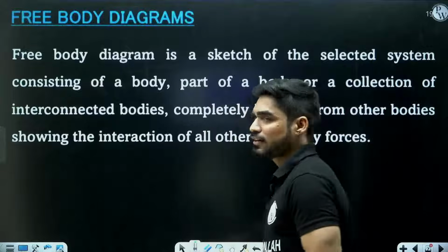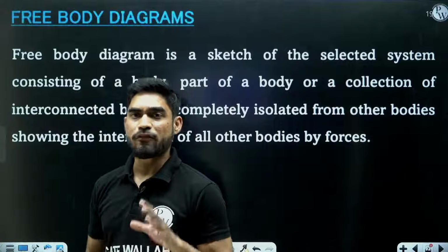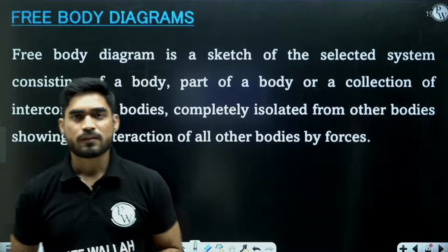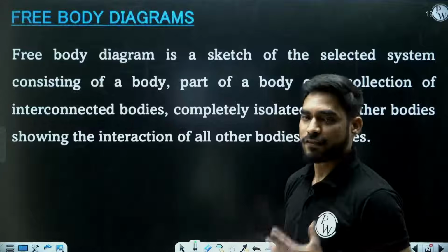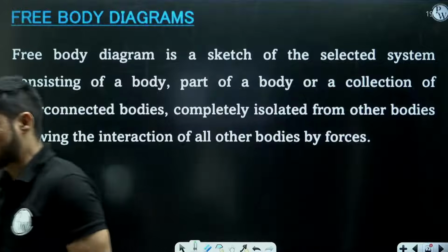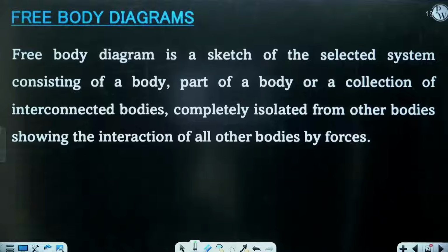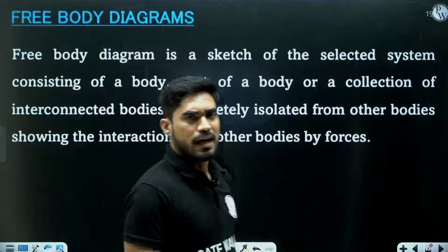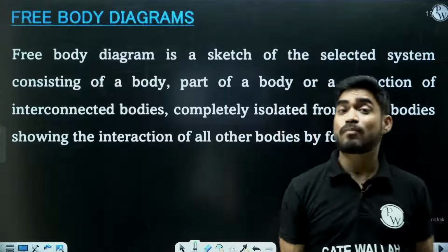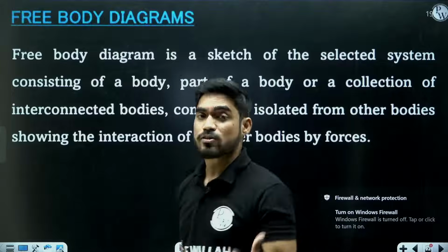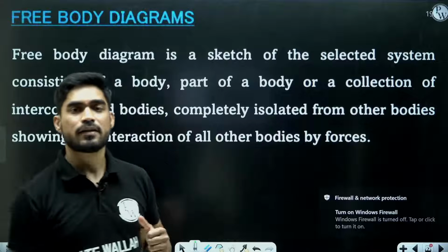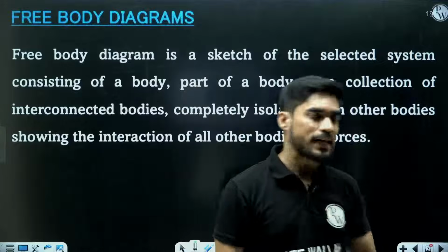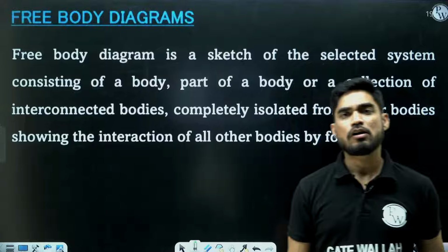So yesterday we saw the concept of free body diagrams. What are free body diagrams? Free body diagrams are the sketch of a system which can consist of a body, part of a body, or interconnected bodies, isolated from all the other bodies. And when you isolate this body from other bodies, you show the interaction between these bodies through forces.